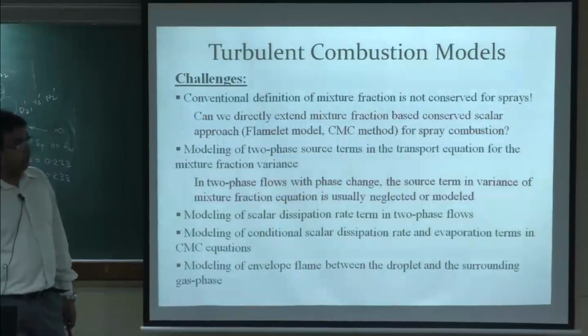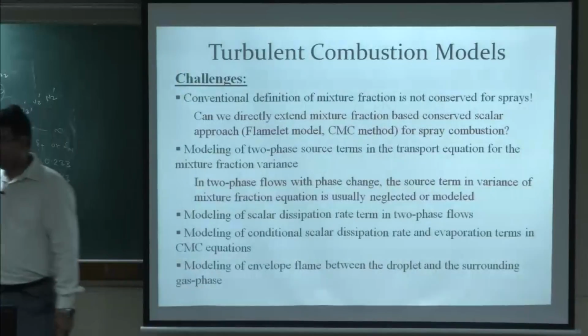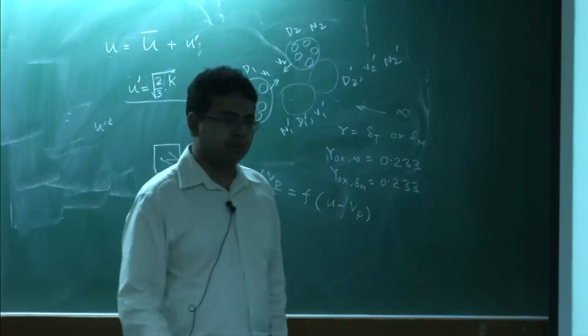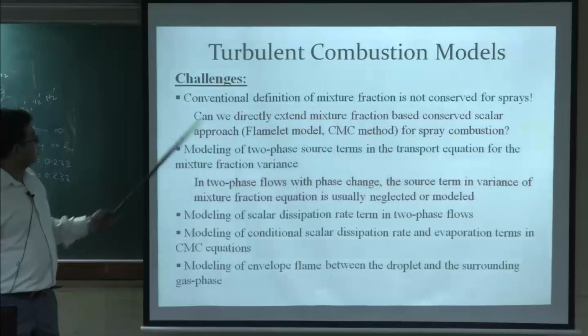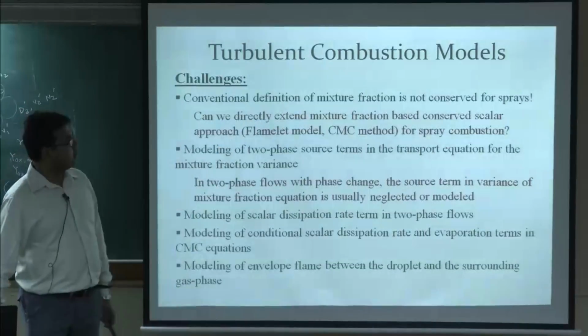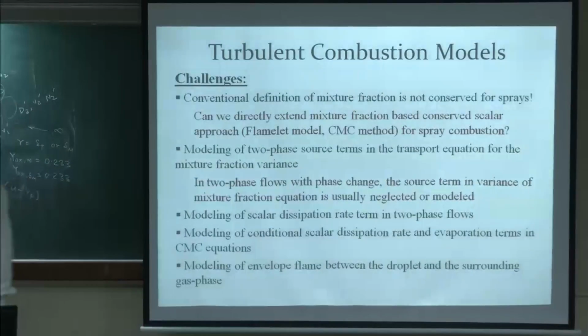Okay, but I will quickly summarize what the challenges of turbulent combustion models are when there is a phase change. Okay. So the conventional definition of mixture fraction is not conserved for sprays. So when you are dealing with a spray, your mixture fraction will not be conserved, because mixture fraction will have a source term due to the evaporation of the liquid droplet.